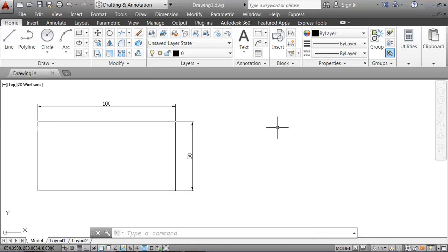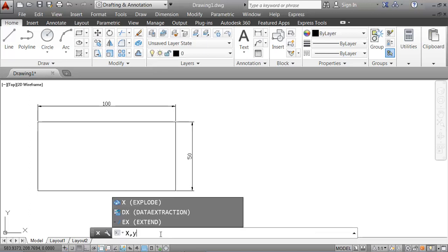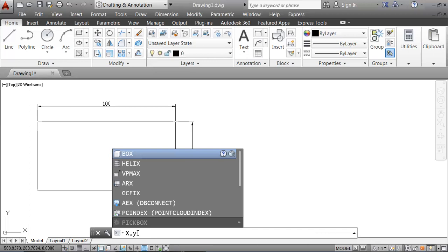And now we're going to look at the absolute command. For the absolute, we're going to use this formula that is down here now. You're going to use x, comma, y. Is it just this? X, comma, y. Similar to relative, but relative has the at in front. Absolute doesn't use at. It's just x, comma, y. All right, x, comma, y.